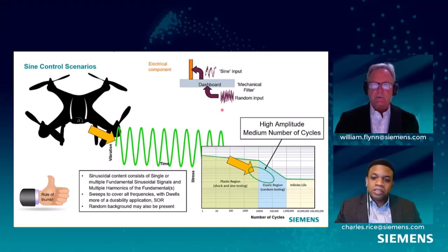I had a quick question. Charles? Yeah, just about the dwells for the durability. Would they normally dwell at the natural frequencies of the structure, or maybe a frequency related to an operating speed? Well, it's typically at an operating speed. Helicopters are a really good application, and they try to characterize the rotational frequencies and identify those ahead of time.